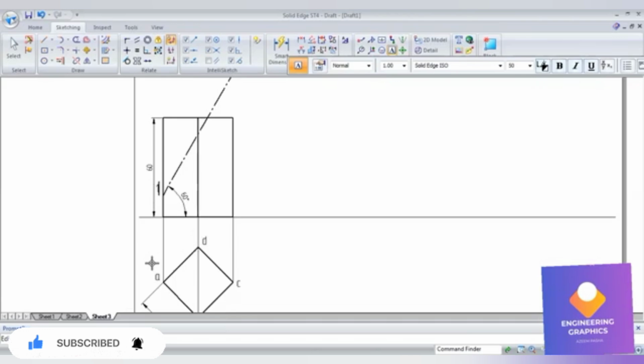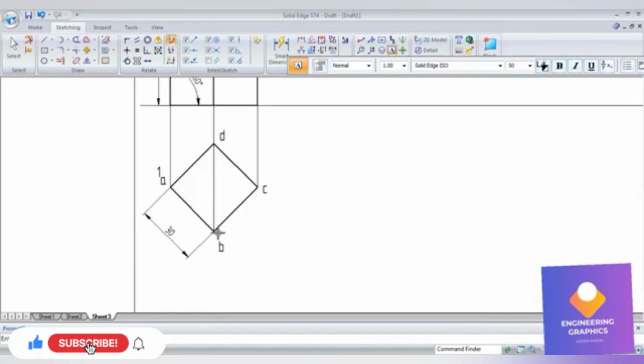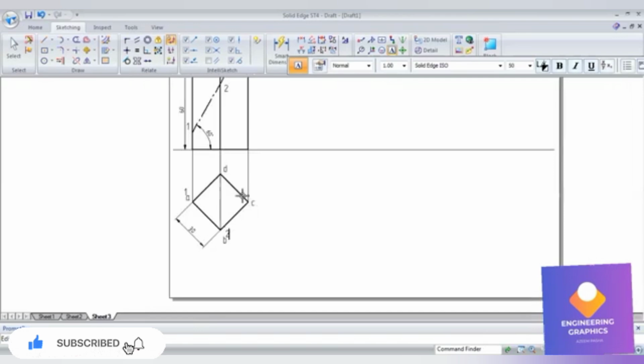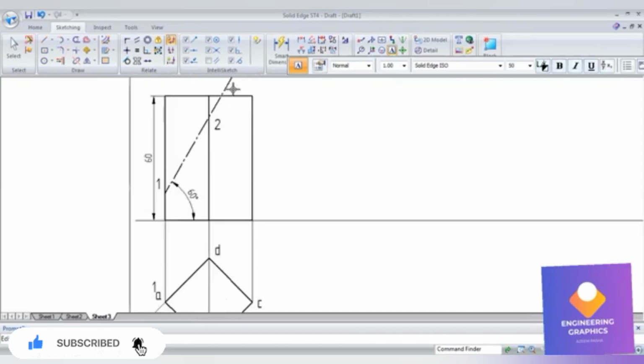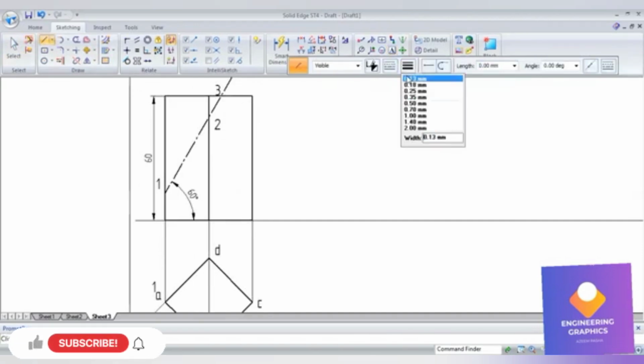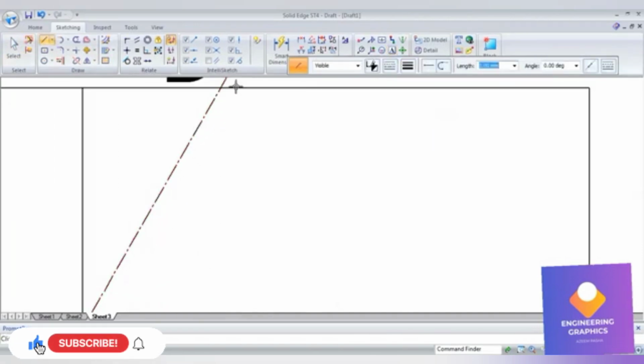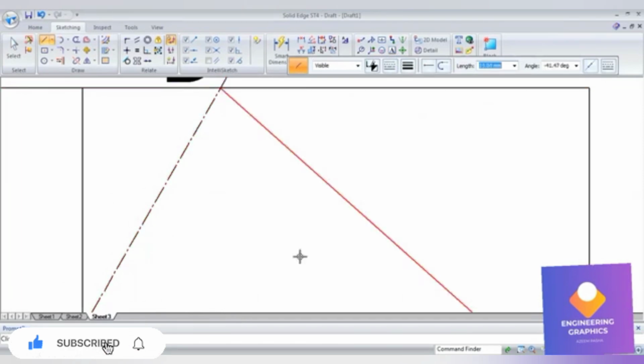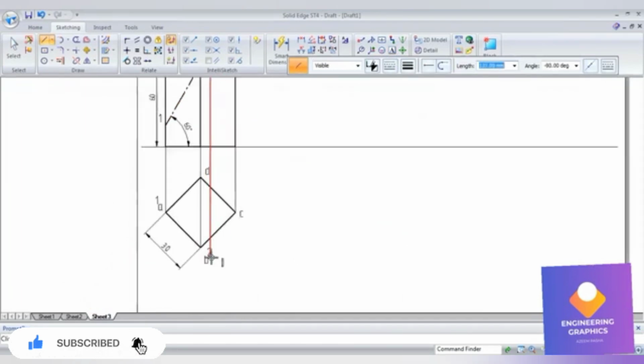Now we can give the naming. Point 1 is where it is cut, on the A edge. Point 2 is falling on the vertical edge B. Point 3 is not falling on C, it is falling somewhere in between B and C. That's why I'll draw a projection line from this intersection.